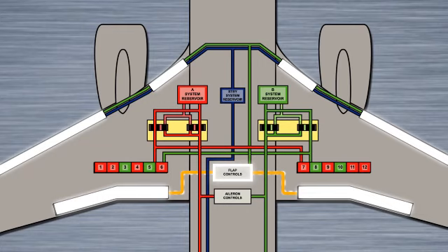During normal operation, the hydraulic system B powers all leading edge flaps and slats. These move with respect to trailing edge flaps in the way we described previously. When the flap lever is moved, the trailing edge system sends input to the leading edge flap and slat control valve. During alternate operation, the standby hydraulic system powers the leading edge flaps and slats and operates them electrically in order to fully extend them.